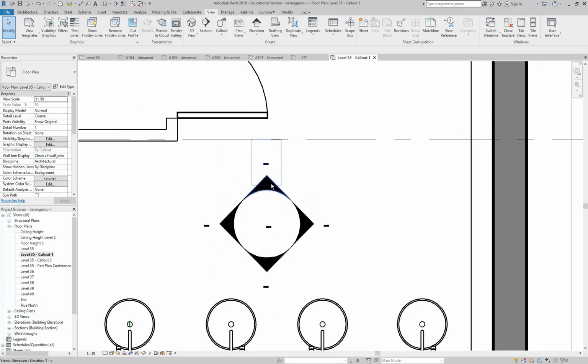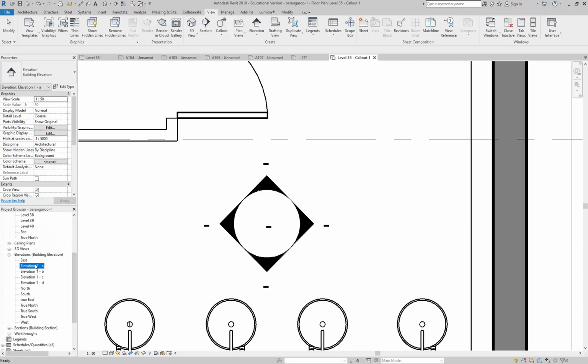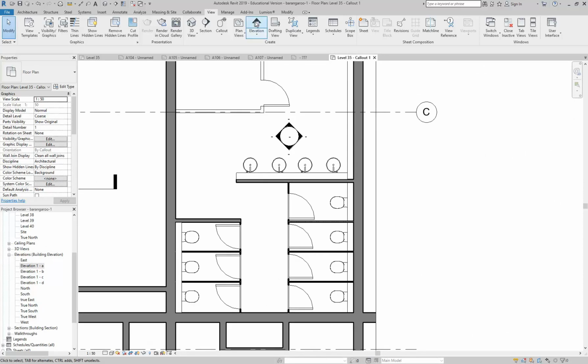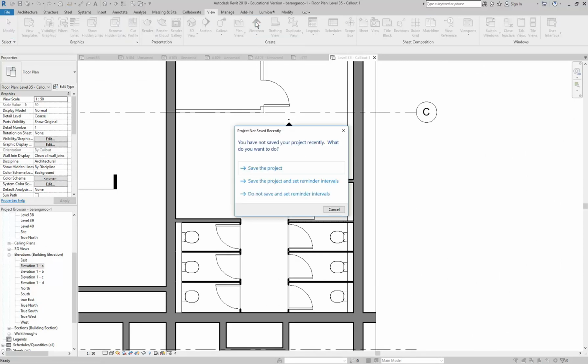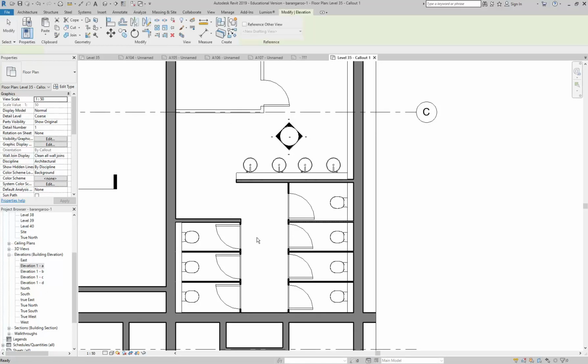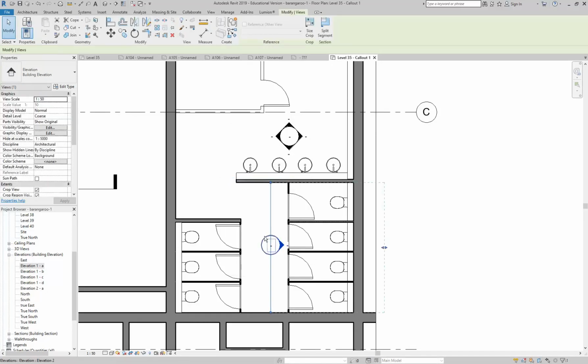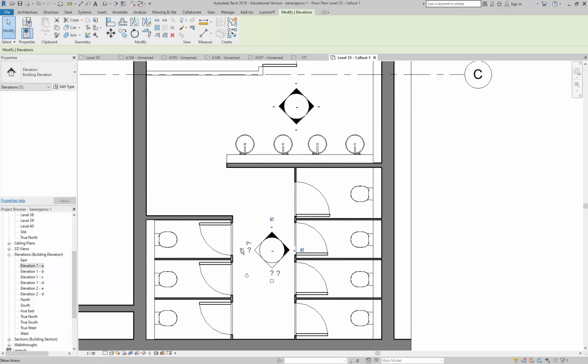So, to get the numbers up, we need to put these views onto a page. When you go to your elevations, it will automatically number them. Elevation 1, if it's the first one, A, B, C, D. And so then, that's it. So if I go and make, but it won't use those. Oh, what? No, they're just in the title. And I'll show you what I do there. So here, if I make this another interior elevation and tick, tick, tick, this is now elevation 2,